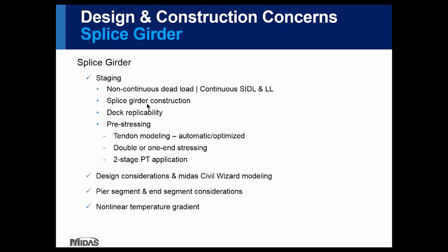And in terms of the spliced girder construction, freely applying and taking out the temporary shoring or the strong backs. And for the deck replacement, modeling the deck composite. And also replacement, meaning I'm actually referring to extending this to any rehab work that can be modeled and analyzed in Midas Civil as well.